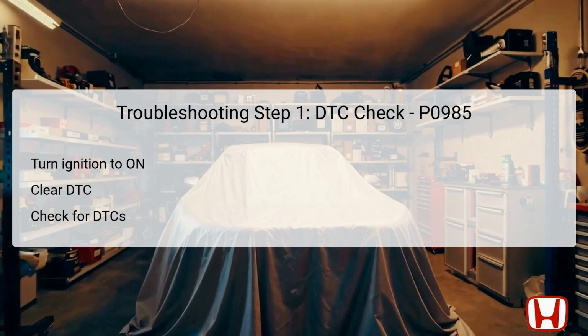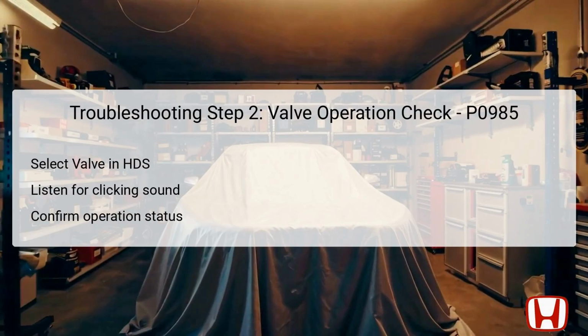The second troubleshooting step involves checking the operational status of Shift Solenoid Valve E via the Honda Diagnostic System, HDS. Access the miscellaneous test menu within the HDS and specifically select the Shift Solenoid Valve E for testing. During this test, you should listen carefully for a clicking sound, which indicates that the solenoid is functioning correctly.